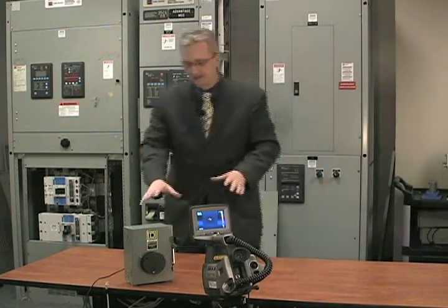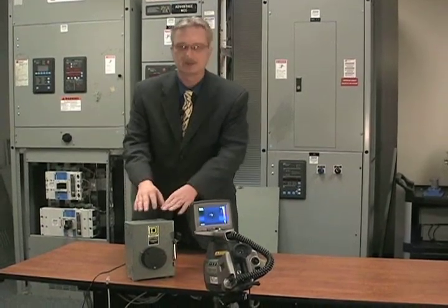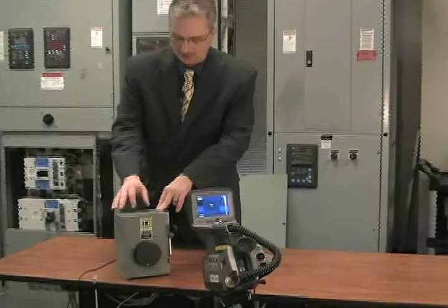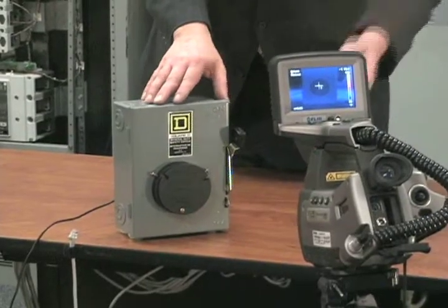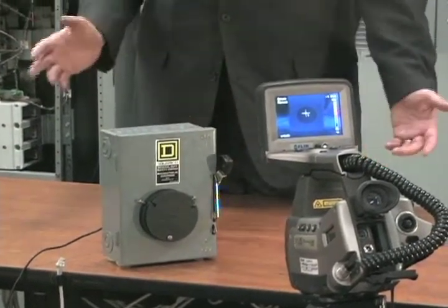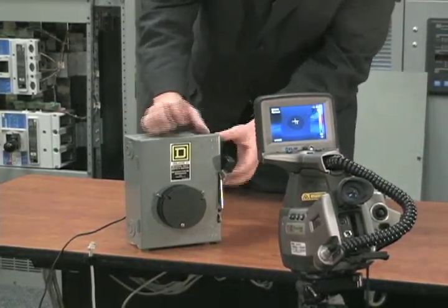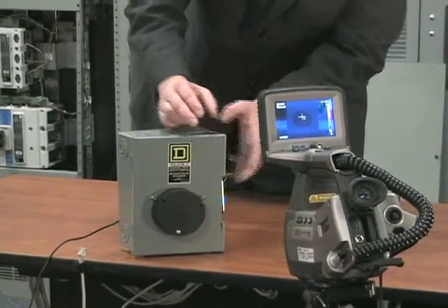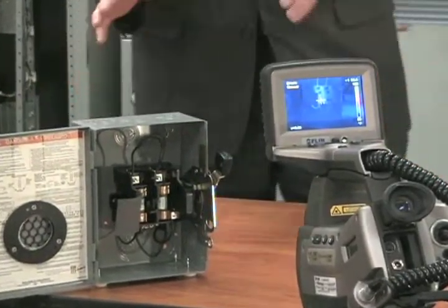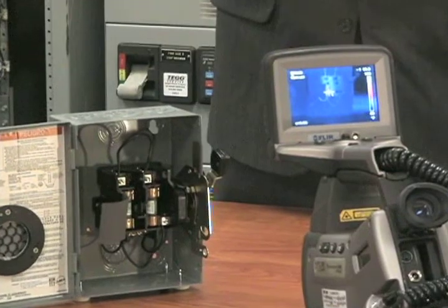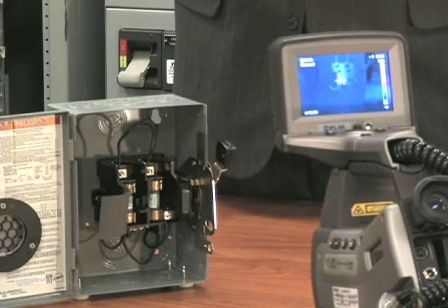In front of me is a little disconnect. This disconnect has a resistance inside of it generated by a little resistor that I have in place. As you can see from the infrared camera's image, on the outside of the cover, it doesn't appear that there's anything warm inside this cabinet. If I open this disconnect, and this is not truly energized, it's actually a laboratory experiment, you can see inside this little cabinet an actual hot spot, a heating source. From the outside, we couldn't see it at all. On the inside, we can see it.